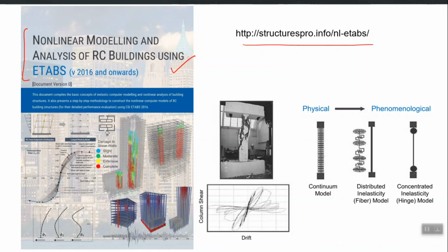So I always make a comparison in the form of required inputs. Just for an example, take a material. Once you define the elastic modulus, one constant number, your elastic material is defined. A linear elastic computer model only requires elastic modulus and Poisson's ratio to completely define a material, because that model will be linear forever.